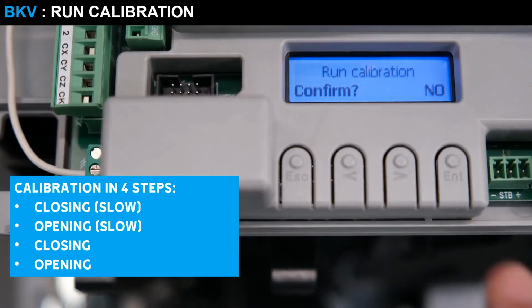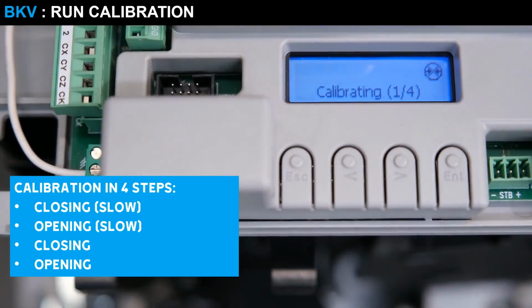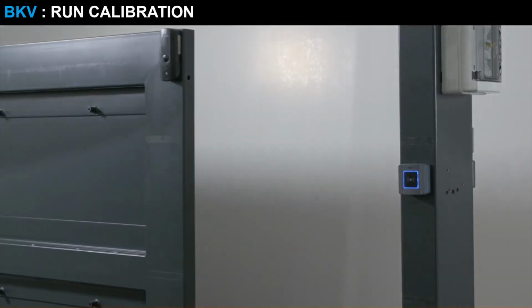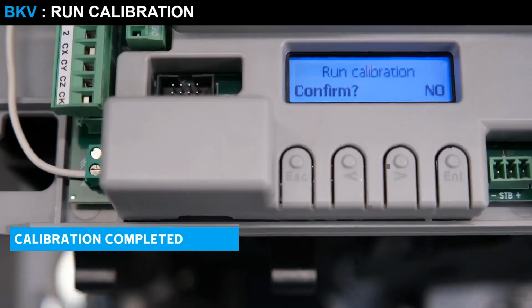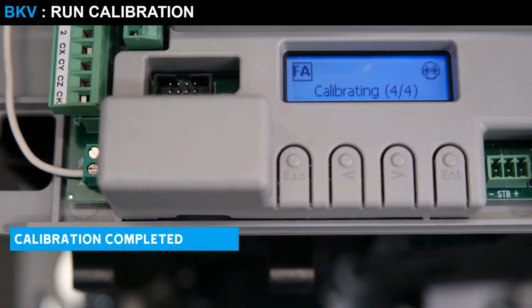Let's move on to calibrate the automation. Press Enter to start the procedure. The calibration will make 4 movements, 2 slow and 2 at normal speed. Once the operation is completed, the automatic gate will be correctly calibrated.